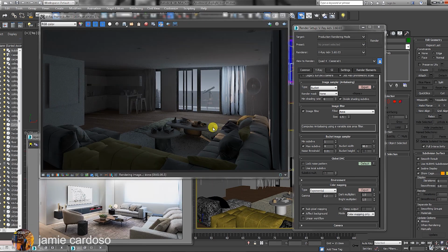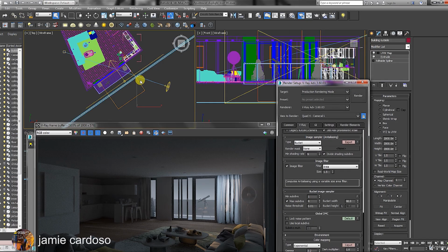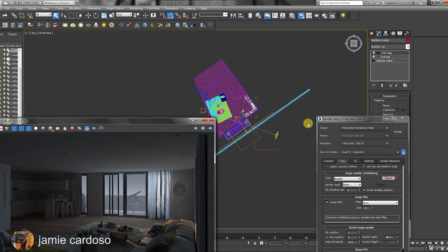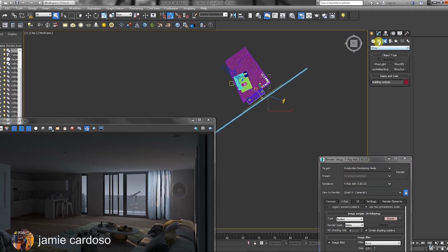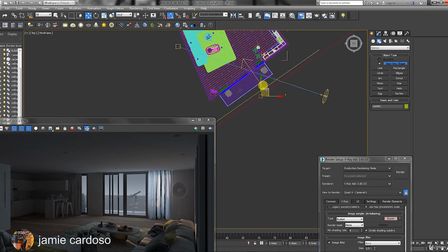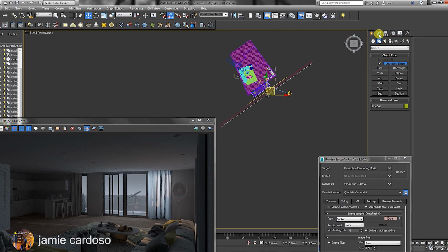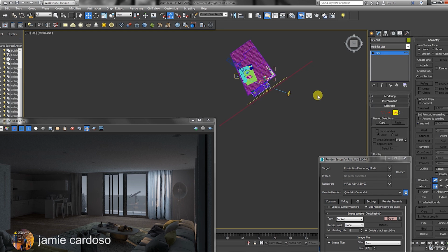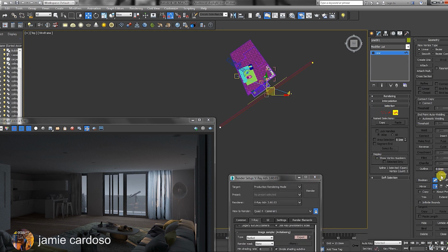The next step is to add a background image outside the glass. There's currently a plane outside without a texture applied. That plane was created by enabling the Splines button, clicking Line, using the snap tool, and drawing a line. Next, open the Modify panel, enable the spline selection, select the spline in the viewport, and increase the outline value to about 10 mm.